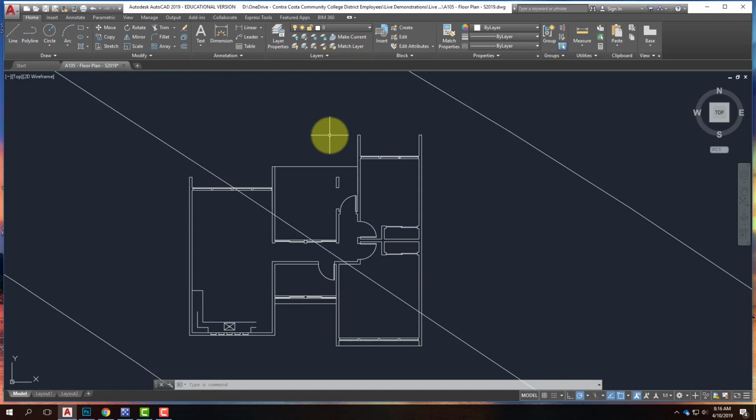And if you don't have some kind of a convention or some kind of an organization, and they start looking at your file and start trying to work on it, they're going to be totally confused as to where all this stuff is. So the common AIA standards for layers, typically if you're working in architecture, your layer would start with an A dash. So if you're doing architectural work, it would be A dash whatever. If you were a civil engineer, you would have drawings, or layers, that would start with a C dash. Does that make sense? If you were an electrical engineer, you would have drawings that were E dash. So depending on who's working on it, it's pretty easy to see whose layers belong to who.